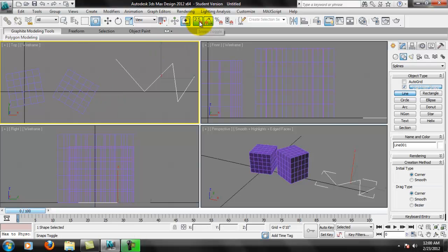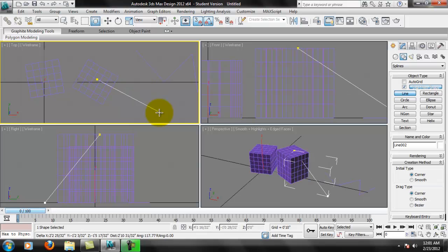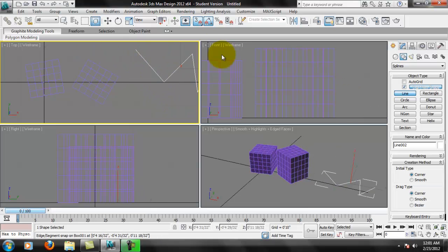So be very cautious when you're using this 2.5 if that's actually what you want to do. Again, because that's going to project through to the actual plane. That's not going to snap to the top of the box. And then the 3 will actually physically snap to the top of the box. So you can see there, it's actually snapping to the top of the box. So that's the difference between the 3, if you're interested.